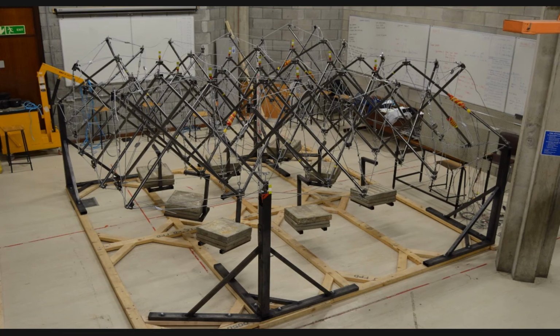The grid was supported on 4 1.2 meter high fabricated steel posts, which allowed the load to be applied and sufficient space for structural testing. Due to the scale of the structure, load was applied in the form of small precast concrete slabs to 8 nodes on the lower grid. These nodes were selected to ensure an even distribution of load, whilst allowing for their safe application from outside the structure boundary. The slabs were attached to the structure via specially fabricated steel hangers, which you can see here.